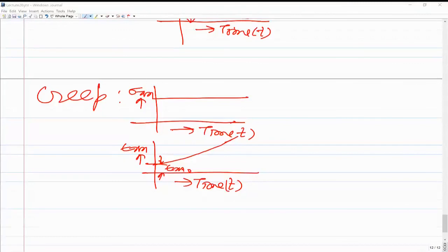So either 0.5 or unity. Okay, sir, so it will be between 0 and 1. Yes, of course beta is going to be between 0 and 1. Zero means the entire step is elastoplastic, and 1 means the entire step is elastic. Okay, sir.